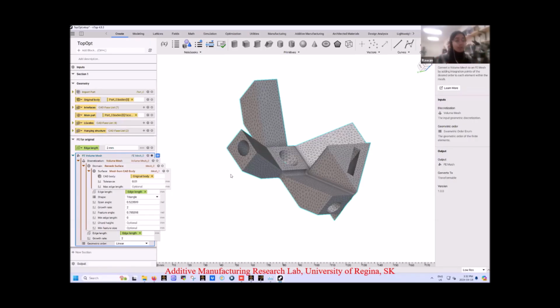However, for some designs, you may have some kind of an assembly where you have other parts and you're linking them and combining them into a single body. So the final result is a single body. However, the software doesn't really accept it as a single body because it understands that some parts are combined together. That's why you may have some reinforcement problems with the mesh, or intersecting sections in the mesh.